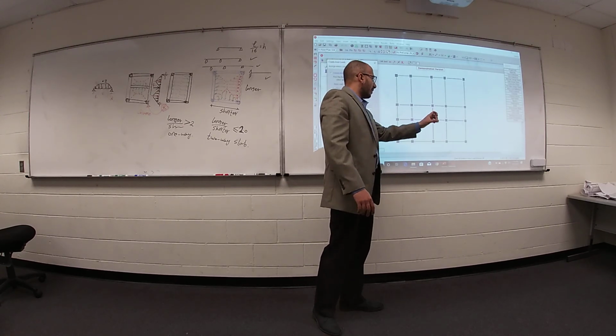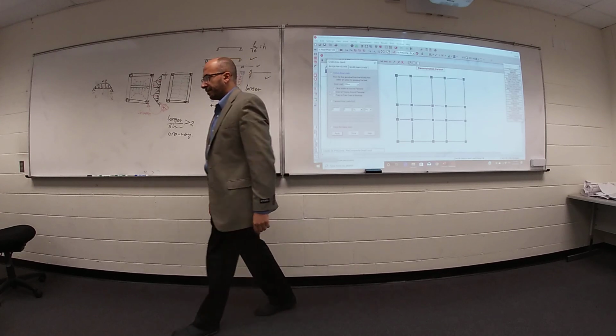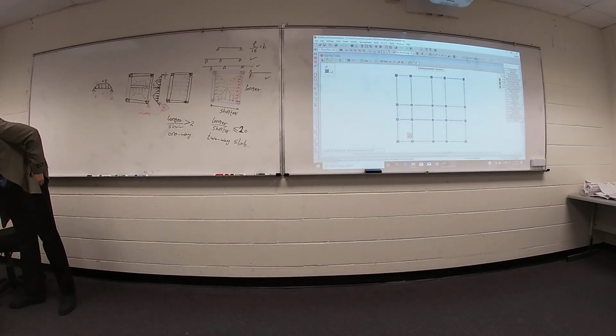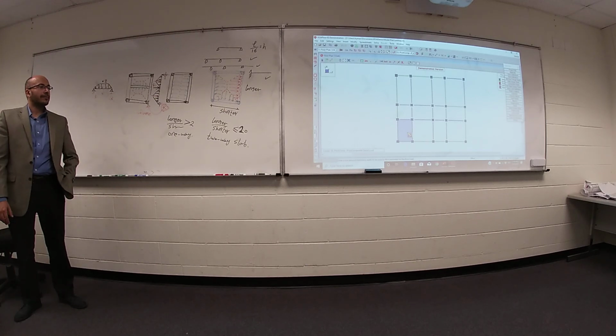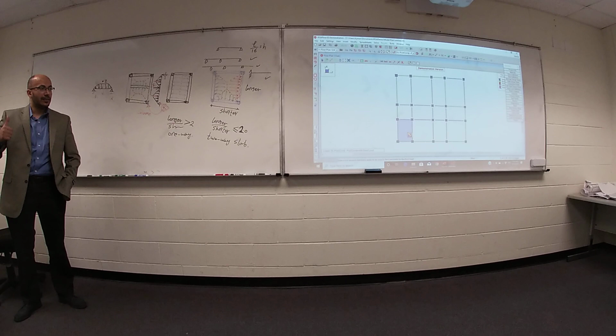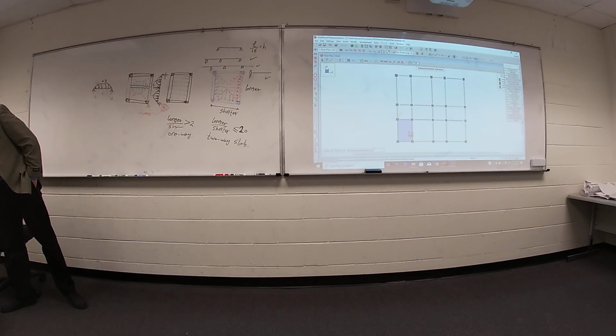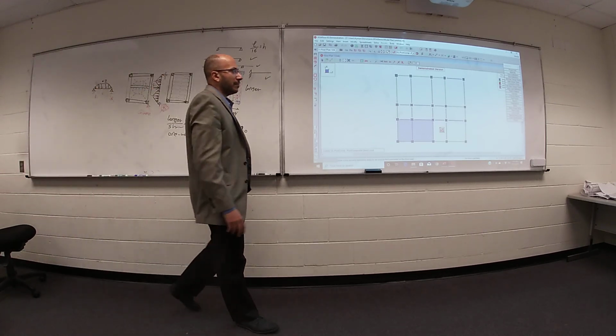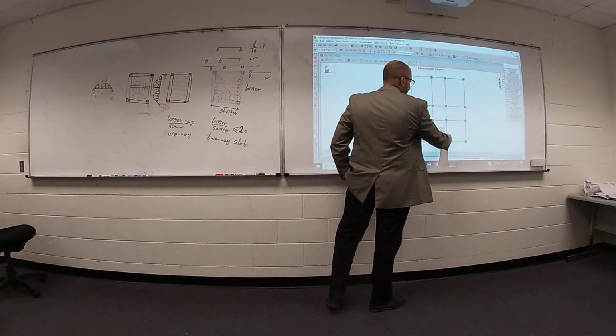If you click here, you define live load on this area. Let's see. Apply. Go ahead. Click. We have live load here right now, coming from office building. Just click at any point inside the perimeter of your panel.